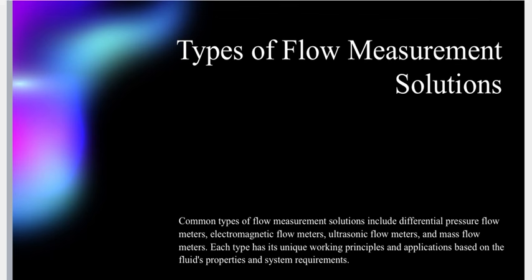The applications are oil and gas pipelines, steam flow measurement, and industrial process control. And the second one, as you see now, is the electromagnetic flow meter, which depends on the Faraday principle. Electromagnetic is the mixing of electric and magnetic. Everyone knows a change in the magnetic field generates voltage, and from the voltage we can calculate the velocity.